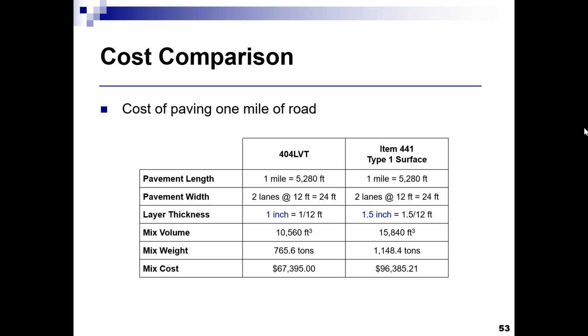Okay, how does slow moving heavy farm equipment do on these mixes? You can use it on locations where you have heavy moving equipment, as long as, again, you have good ramps for entrance and exit. You don't want the heavy moving farm equipment to be trying to jump on the road from a farm on these mixes, because then it might cause a little bit of damage. But again, all the counties that we talked about are basically rural counties where heavy farm equipment are available and are being used. So you can use them actually on these roads.